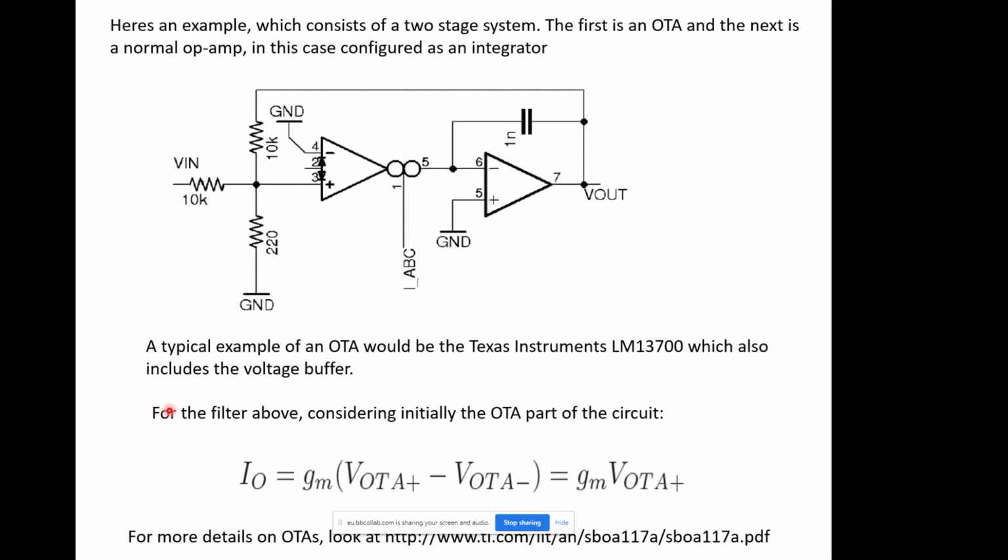So this is something that might be done to create a single order, first order filter type structure using an OTA and an op-amp. So you can see this is the operational transconductance amplifier. It's got a differential input like an op-amp, it's got a triangle like an op-amp, and then it's got this current source as the output and another input here, which is the bias current. So you can show that we can actually change the bias currents of this stage in here.